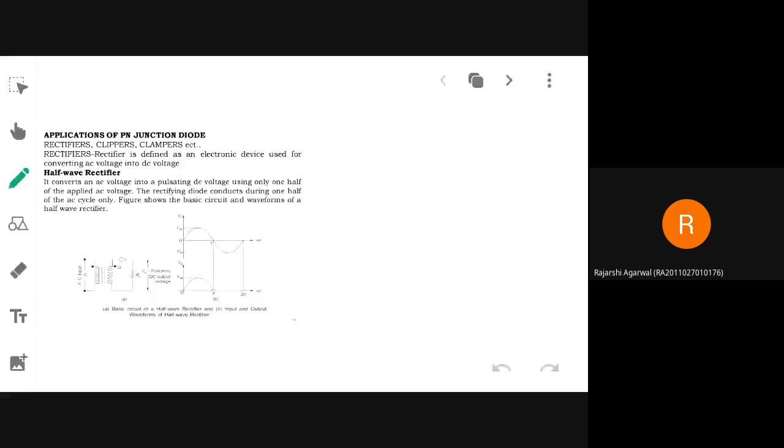Alright. So both are two terminal devices. And how do they differ? Doping wise, which is heavily doped? Zener diode. Okay. So which device is capable of operating in reverse bias condition? Zener. The ordinary diode is not capable of being operated in reverse bias because it will not be able to cope with the power dissipation that happens at the junction. So you cannot operate the PN junction diode in reverse bias.